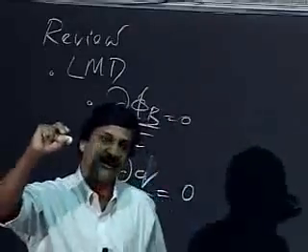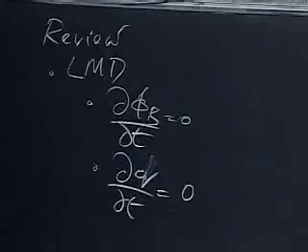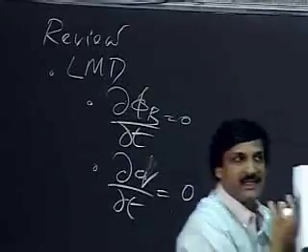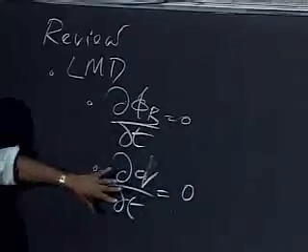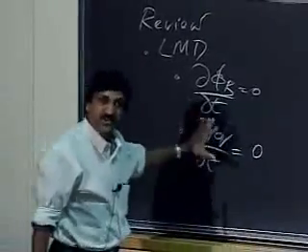So if I took any element that I called a lumped circuit element, like a resistor or a voltage source, and I put a black box around it, then the net charge inside that is going to be 0. Now, this is not true in general.